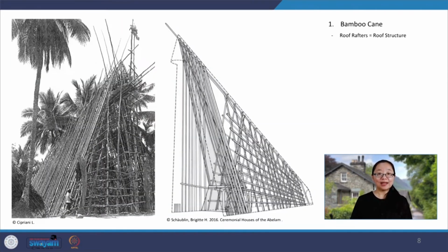The bamboo canes are placed on each side leaning against the ridge pole. The rafters are stabilized from the inside with the help of 2 or 3 bamboo battens on each side. The poles are subjected to compression and bending loads, resulting in deformation under their own weight in particular, and under additional external load, which must be taken into consideration as part of a structural system.